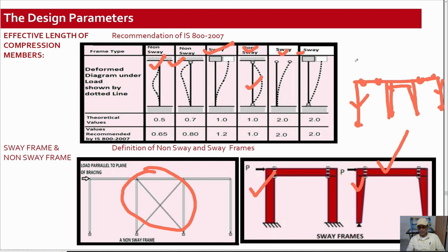You can run the model for a second order analysis and see if the lateral deflection in the second order analysis exceeds the lateral deflection obtained from the first order analysis by 10%. Then a P delta analysis is required, or a direct design method can be applied to design a column like this.